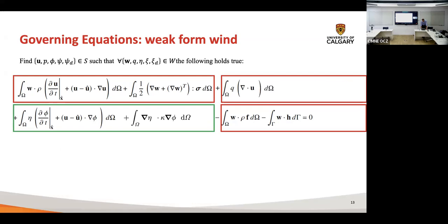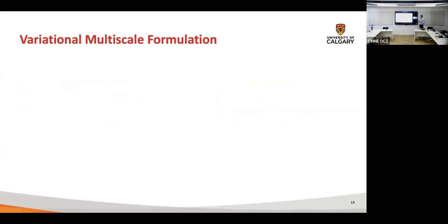Okay, and your continuity equation simply reduced to the divergence free velocity field, and you have an additional Boussinesq term that you need to deal with. Okay, so you can see just a few terms, turn it on, turn it off. So indeed, we are using exactly the same formulation, exactly the same set of stabilization constant, etc., which I will talk in a minute. Okay, now, as you know, Galerkin form is not enough. Okay, it is unstable in the presence of the advection, and you have to deal with the turbulence somehow.